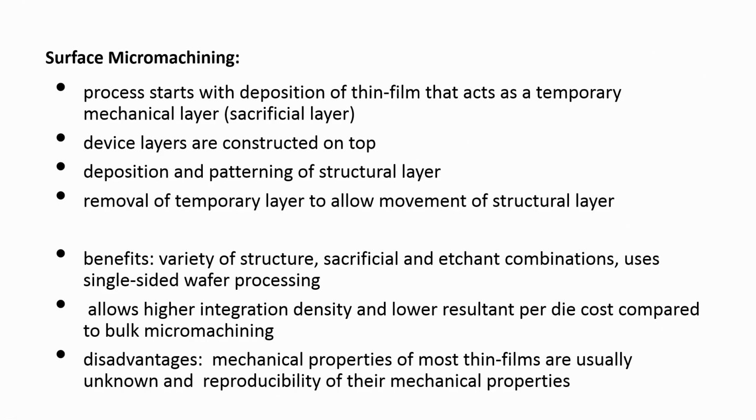So, if it is single side polished, the cost of fabrication will be less compared to a double side polished wafer. Then the further advantage of surface micro machining is that it allows higher integration density and lower resultant per die cost compared to bulk micro machining, that is the advantage.